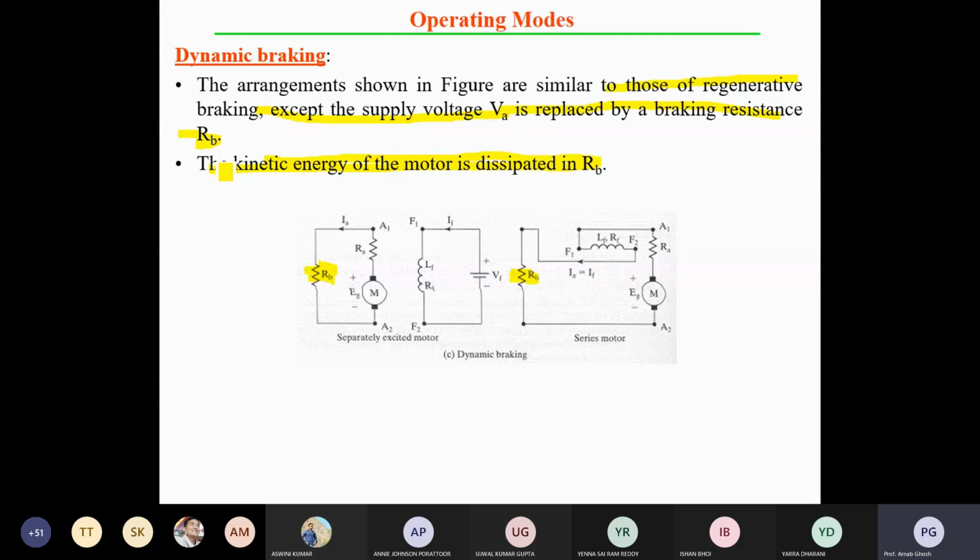So that's why in the normal EMU, our city ride, we are using the dynamic braking concept. So a lot of energy will be wasted over there. But in mainline service, we have some capability to reverse back some of the additional energy to the mainline, means the overhead line of the mainline track. So in that case we can follow regeneration, then dynamic braking. But in local city ride, we should go directly for dynamic braking.